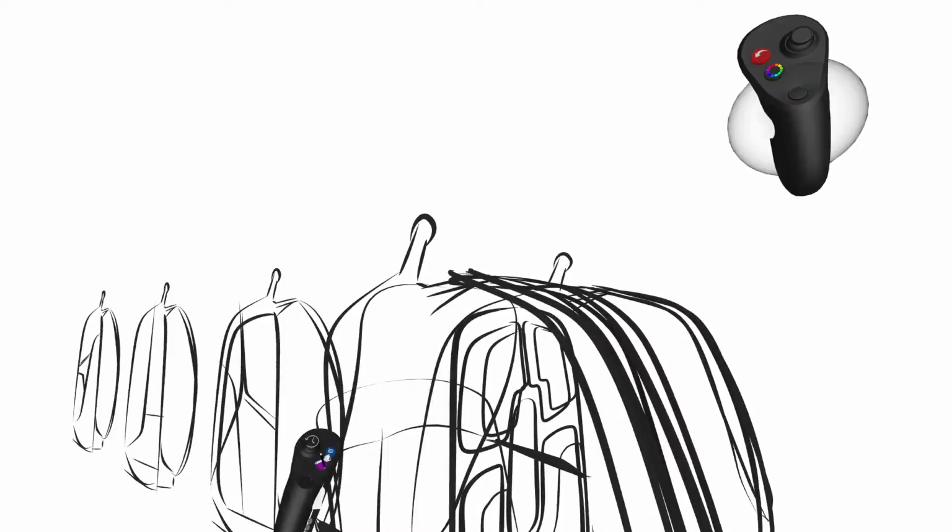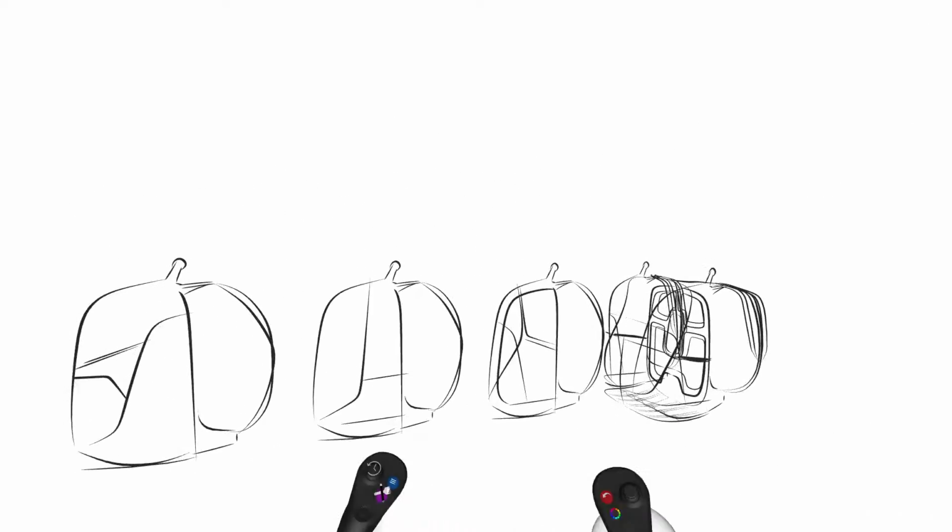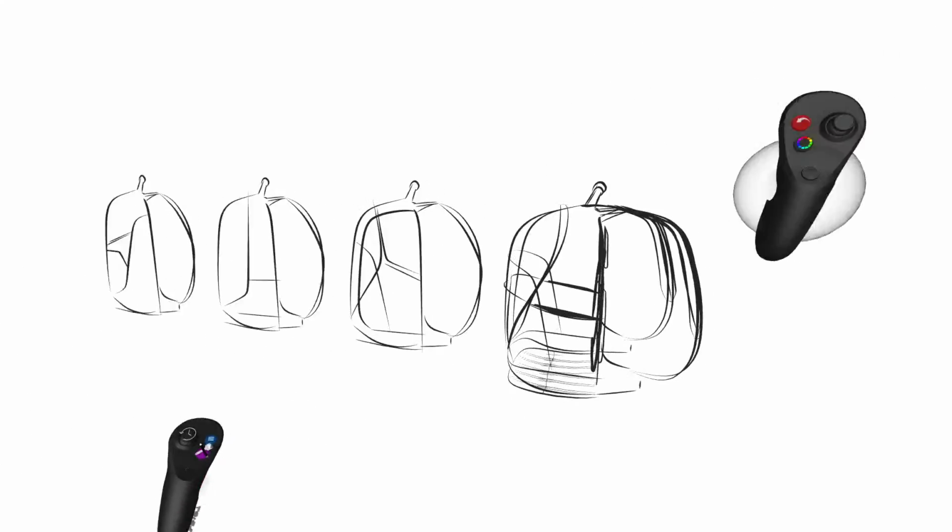Right now we have a flat texture on our strokes, but if we wanted, we could go to a basic texture and now I've got a little bit of shading, but it's pretty black, so it's hard to see the shading on these strokes. But anyway, this is just some best practices for sketching in Gravity Sketch. Feel free to bring in reference images as well, and sketch off of those.